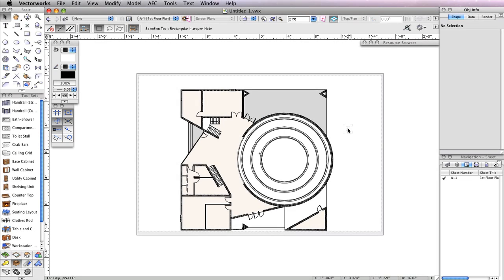Since sheet layers can display more than viewports to present your final project, let's go ahead and add a title block and a sheet border as well. Select the Sheet Border tool from the DIMS Notes toolset, and double-click anywhere on the sheet layer.